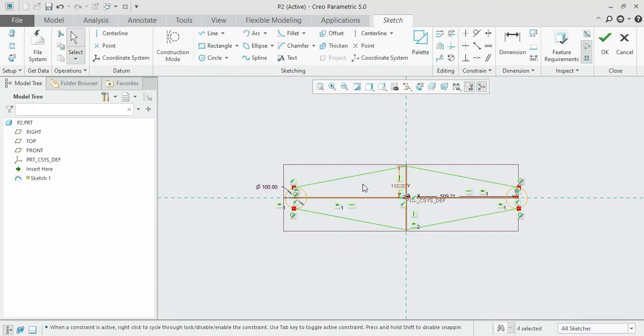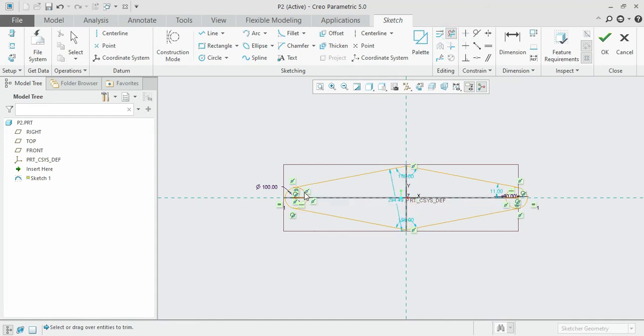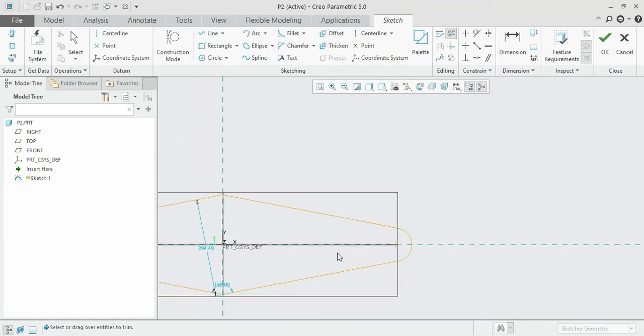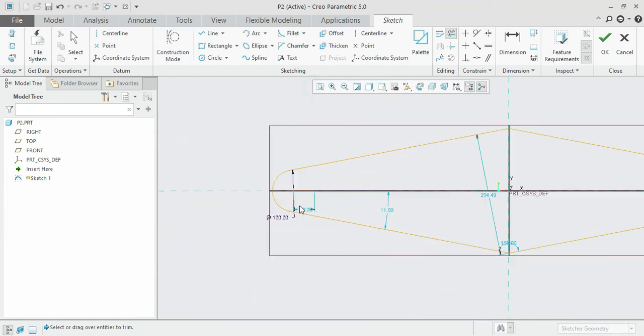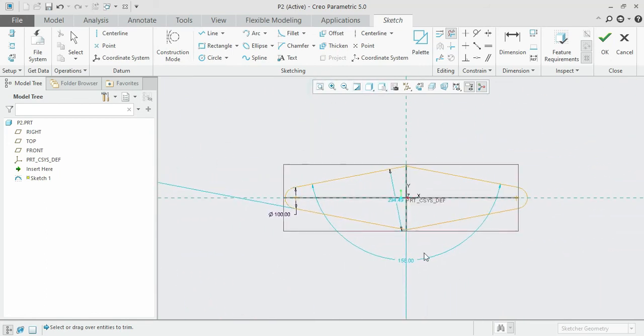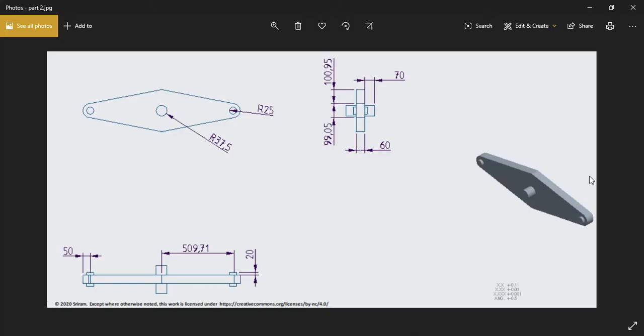Right, finished. Now remove the unwanted lines. Remove the vertical unwanted and the horizontal unwanted. Similarly, these two circular arcs we don't need. The residue lines are removed. Okay, now we have finished creating this one. The basic front view has been created. First we shall extrude it. The total distance of extrusion is 60, right?